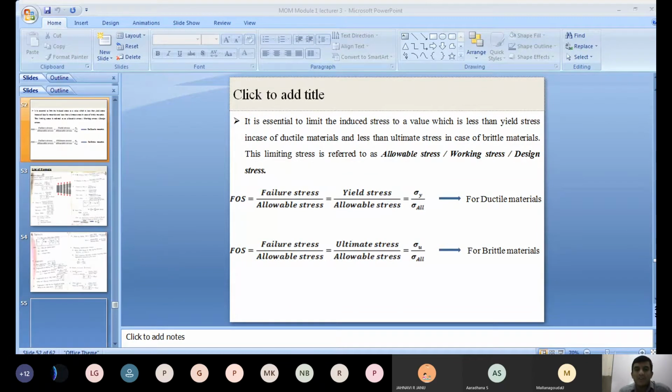Again, if you take the same component made of the same metal and conduct the experiment again, you get another value, with slight changes in the values when you conduct the test, because the materials we use are not pure engineering materials. Those are called impure materials. That's why in India we always use a factor of safety greater than 1. It may be 2, it may be 3 also.